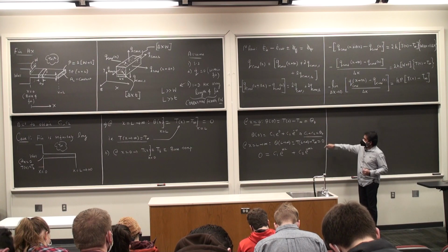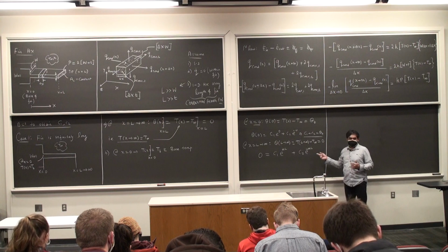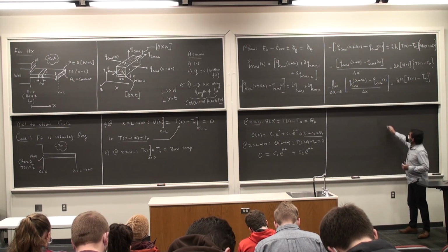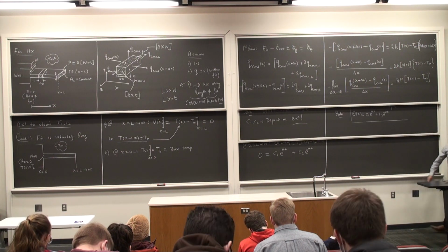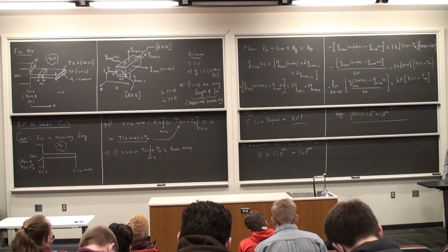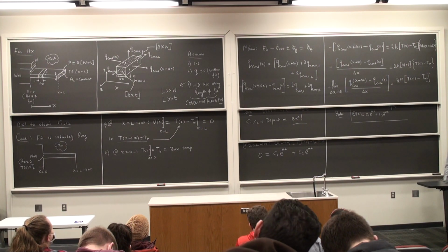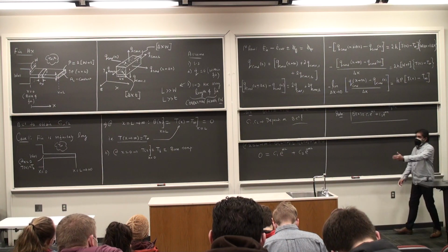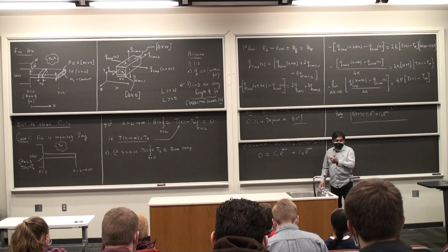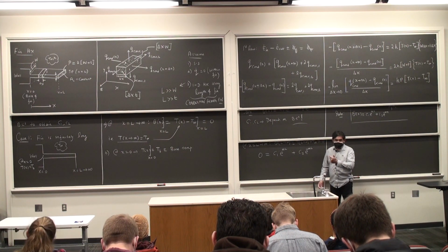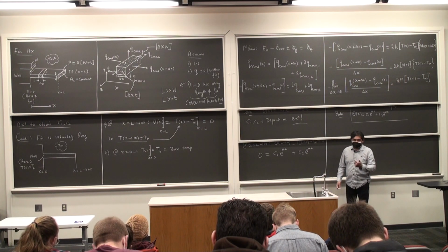This is 0 here. All I'm doing is, instead of theta, I'm substituting it into the solution for theta of x, which we obtained previously, which is right here. And now we are stuck. So what do we do? The left hand side is 0. The right hand side contains two terms. One is e to the power mL and the other is e to the power minus mL. And as L tends to infinity, one of those terms drops off, the other term blows up,